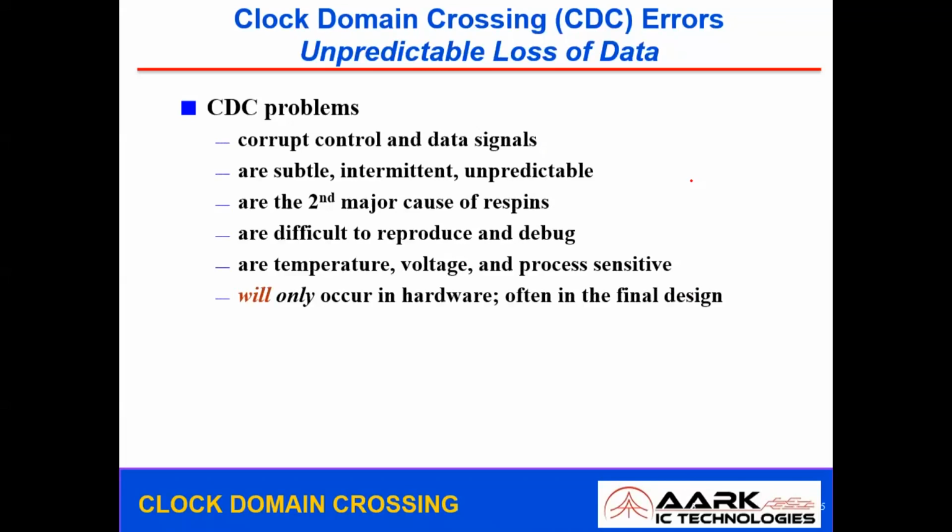When you look into any RTL design, the RTL design basically is going to have two paths. One is called a control path and the other one is called a data path. So when you take a multiplier, or a UART, or a USB, or any complex design, you'll have a data path and you'll have a control path. These two are different, so there are two mixes of signals: control signals and data signals.